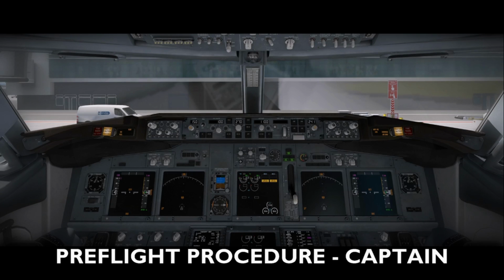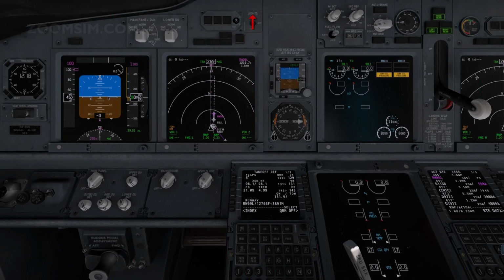The captain normally performs this procedure. The first officer may perform it if required. Master lights test and dim. Test. Verify that all system annunciator panel lights are illuminated.